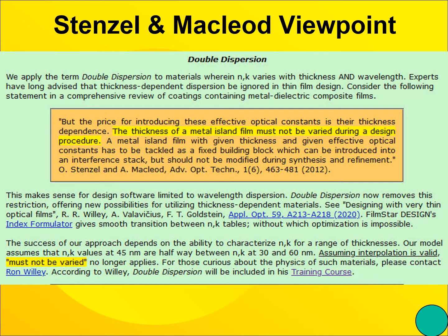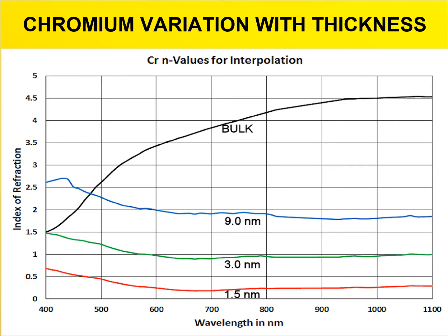So that if they really would benefit by a 15 nanometer layer, it was not something they could use in their design. But what we've done here recently is to overcome that limitation so you can design fairly reliably with any thickness you want from the minimum that you've characterized up to the maximum, where you interpolate between the ones that you have actually produced to get a good estimation of what you would produce at some intermediate thickness.